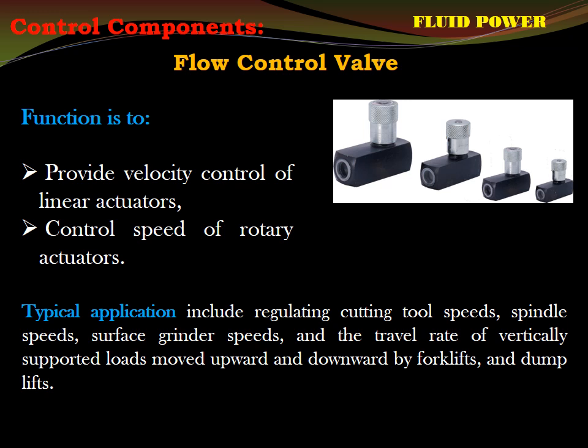So what I have said is it controls the volume rate of the fluid. We can say its function is to provide velocity control of the linear actuators, as well as to control the speed of rotary actuators, as shown here.